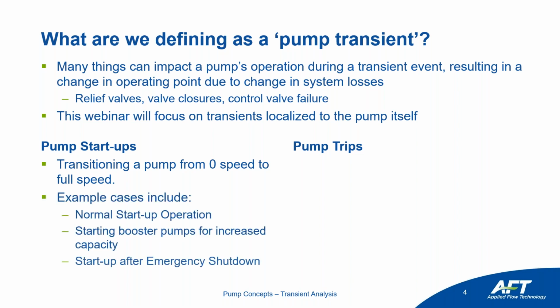So some example cases for pump startups is normal startup operation. So you can't install a pump at steady state. You can't install a pump as it's already running. So every pump that you install will see at least one pump startup event in its life. That means that this type of analysis applies to every sort of system. Let's say you're building out your AFT Fathom model for your steady state operation. It's very easy to take that same system, bring it into AFT Impulse, model the startup event, and look at a lot of these same considerations that we'll talk about in the next slide.